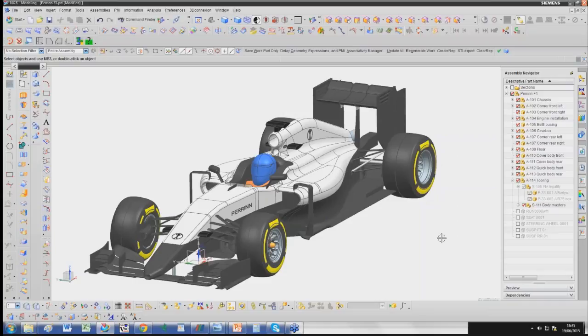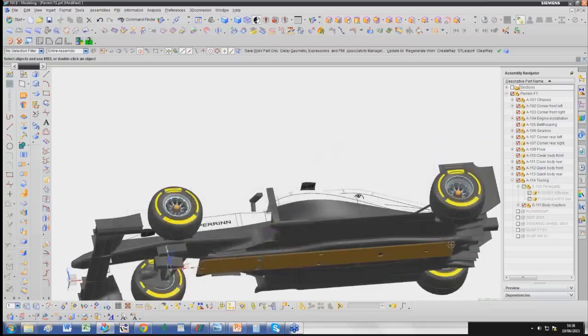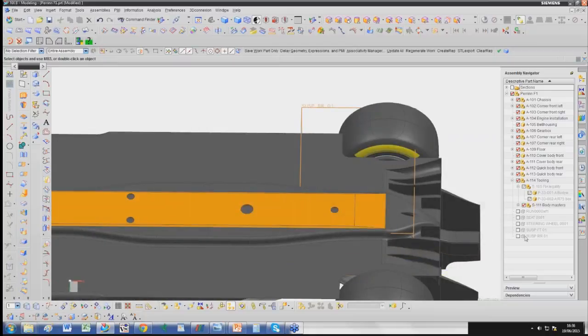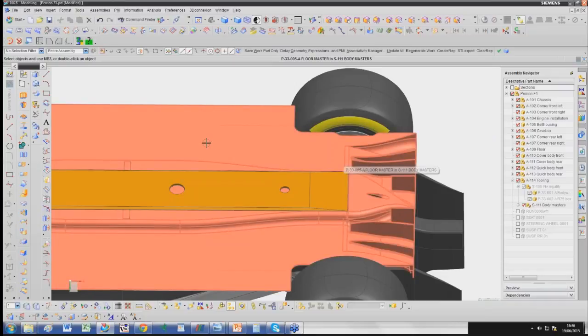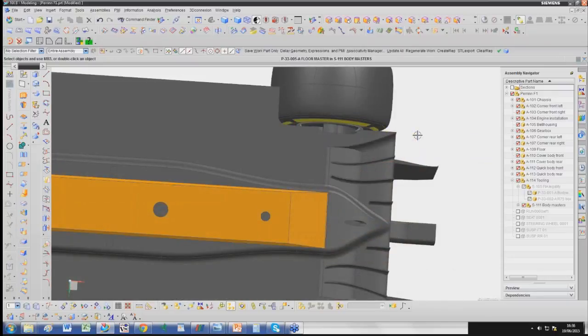Okay, Milad? Bruno noticed that the diffuser starts about the middle of the rear tire, and he wants to know if that's a regulation thing or your design choice. Yeah, it is the regulation, definitely. As you can see, the diffuser starts here, on this fillet here. We would all love to have the diffuser starting further forward. That would make the car much faster, but no, we can't. So the diffuser starts there, and in terms of height, the maximum is here. So this is by regulation, yes.